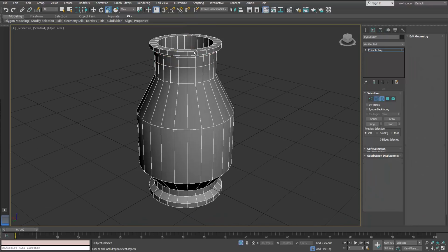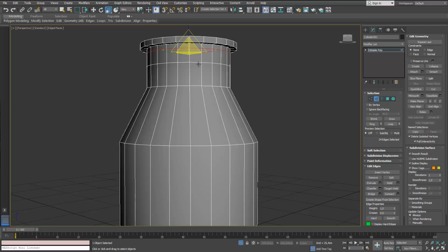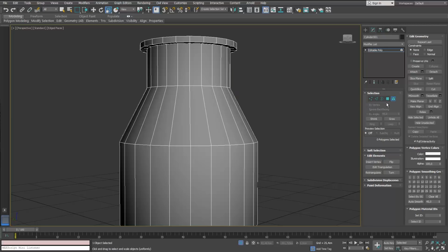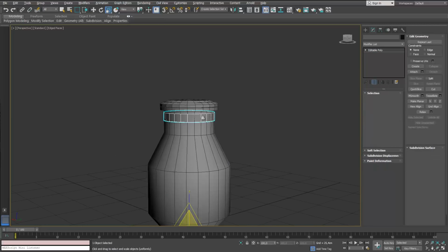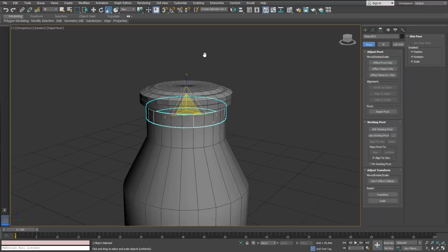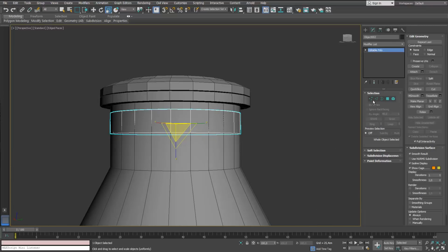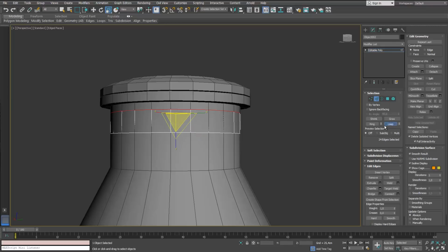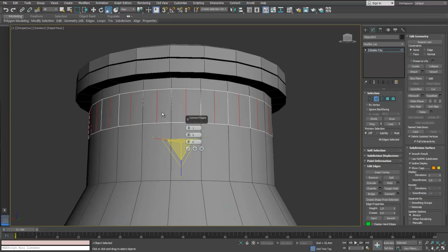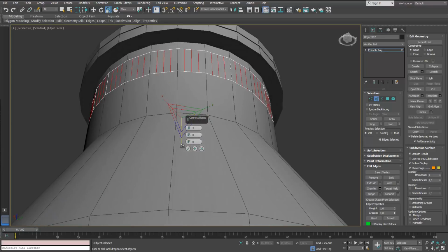Okay, right now we need to remove the edges that we created for this purpose, and we're gonna reset the smoothing groups, because sometimes we can see some of these issues taking place, which is not that big of a deal. All right, so for now we're gonna work on this piece that we call the floating geometry, and first of all, we can try to add some edges in between, which is gonna be a nice thing to do.